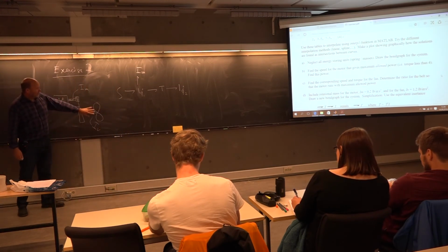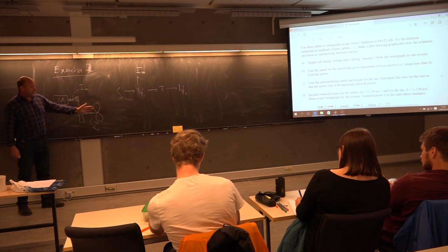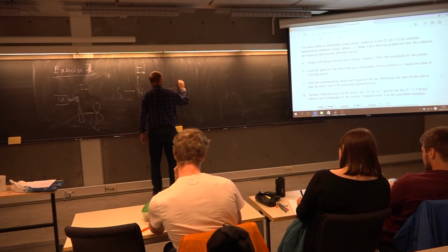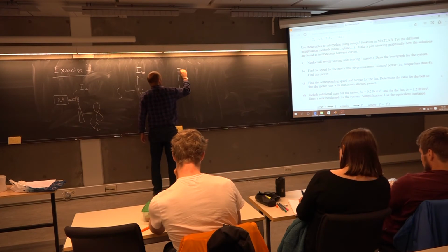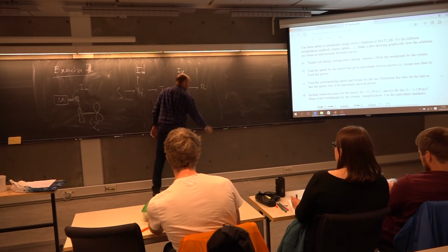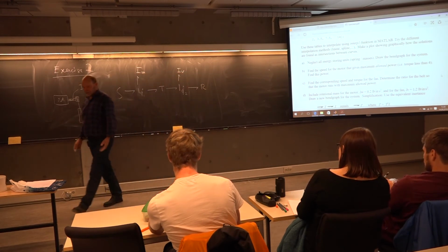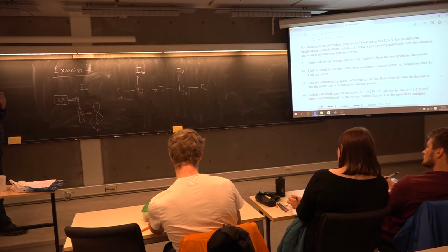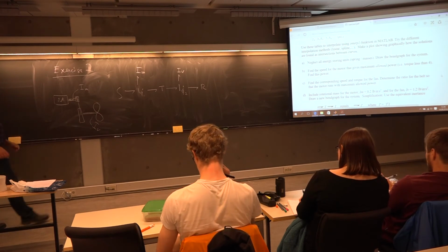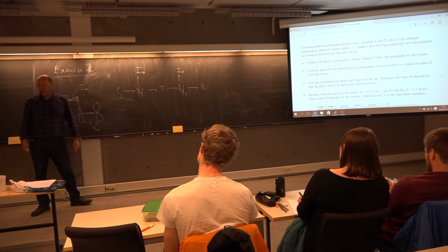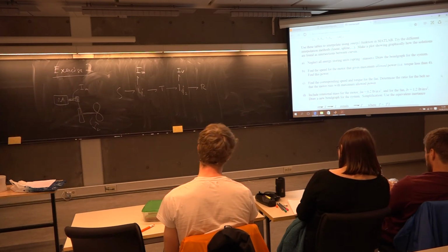And here we have two things. We have a mass, yes, of course, Iv, but also the load, the total resistance to rotate this fan will now enter into the problem. So this actually will be the bond graph, the answer to this part of the exercise.